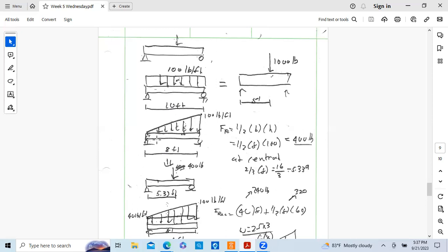In other words, it's going from 0 to 100 pounds, uniform varying. And the way we label it is 100 pounds per foot at this particular point. So again, we don't want to deal with this. What we want is a single beam with this as a single point. And so what we have here, this was a rectangle, base times height.